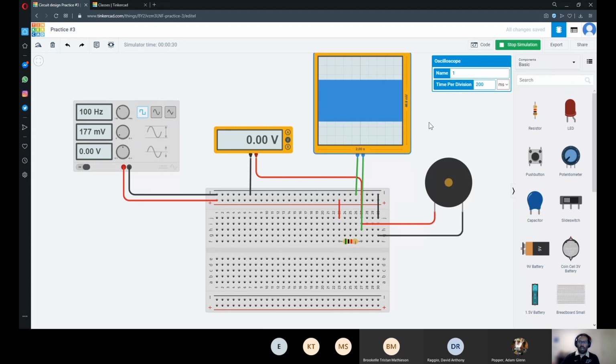this is something that can happen in the lab. You just see like a big piece of signal that you can't really see what's happening. So that's when you have to decrease your time per division to be able to visualize it correctly.